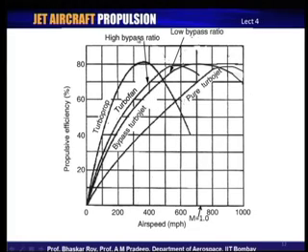Now, the high bypass turbofans, which take over from the turboprops, take it to reasonably good propulsive efficiencies, and then when it comes pretty close to Mach 1, they also start going down in efficiency, and close to Mach 1 their efficiencies become slowly uncompetitive compared to, let us say, the low bypass ratio turbojet, or one may call them turbofan engines.